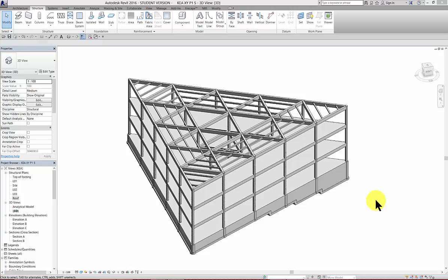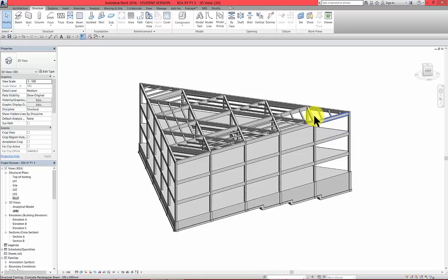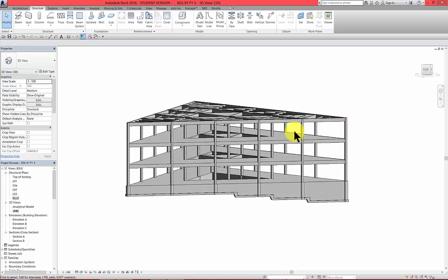The next part of the building is going to be a sloped roof. To do it, we need to first set up and change the heights of the columns, then the beams, create the slopes, and then create the slab that will follow the slopes. We can start to change the heights of the columns around.